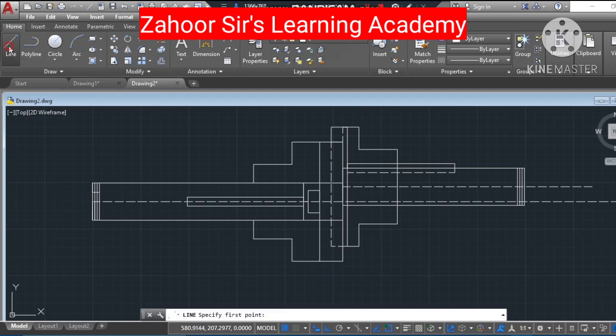So the same could be done here also. Okay, I'll pick a line. From here it will be going up 12.5. So 12.5, then pressing enter and dropping it there, then escape. So this is how we have done it. I could copy the same things here.